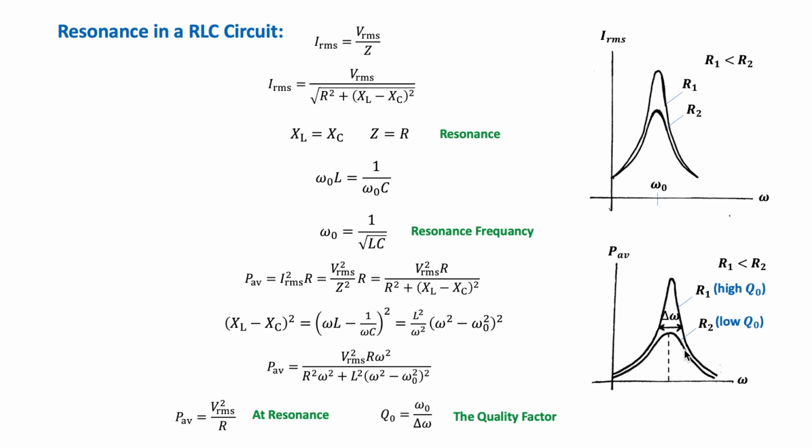And one application of this circuit is the receiving circuit of a radio. So when the resonant frequency of the circuit matches that of an incoming radio wave, then the current in the circuit increases and the signal is amplified and given to a speaker. So the radio receiver resonant frequency can be varied and tuned to a different station, which means to a radio wave of a different frequency, by varying the capacitor in the circuit.